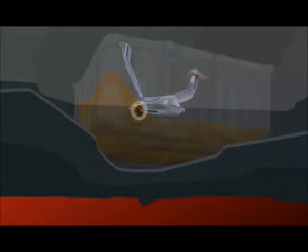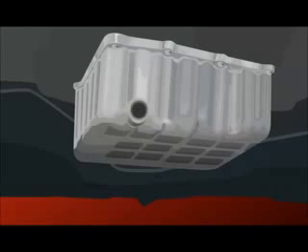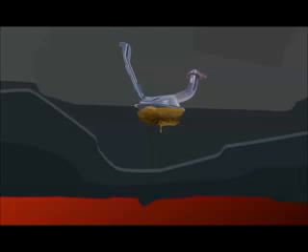These steps will provide a tight seal on the oil pump suction side, preventing oil starvation at startup. Finally, low oil pressure occurs when sludge builds up on the oil pickup screen, reducing oil flow to the pump. On some engines, you may be able to inspect the pickup screen by removing the drain plug, but the inspection typically requires oil pan removal.